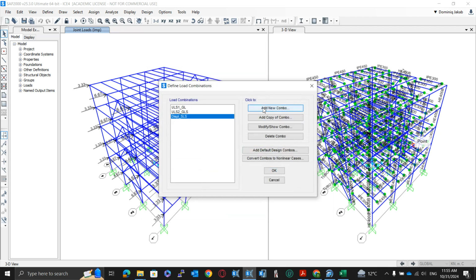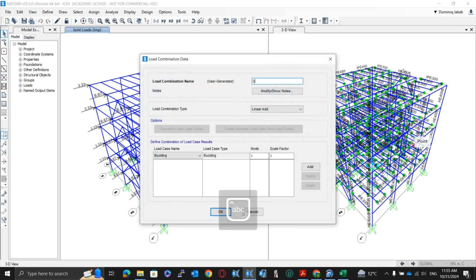And let's have another one for displacement at ULS or significant damage, which is dead with 1, live with 0.3, and seismic action is C multiplied with Q. Let's take C for the first iteration as 1, and it will be Q, which is 6.5.